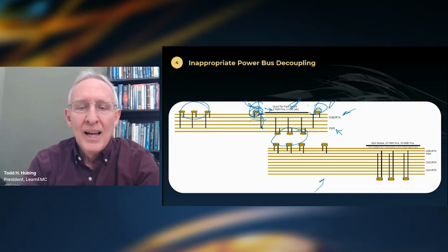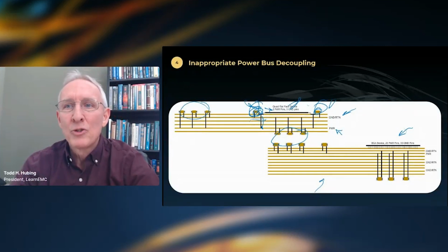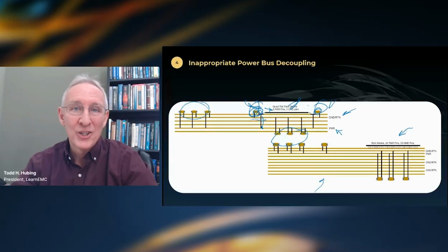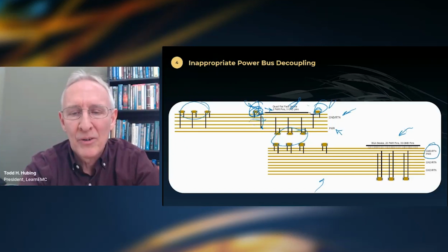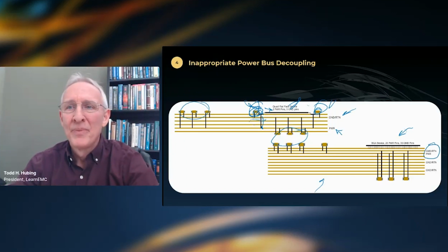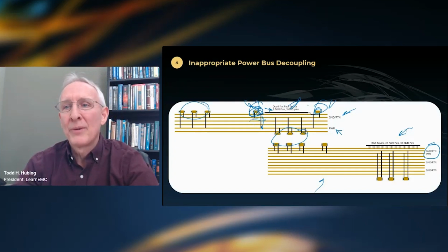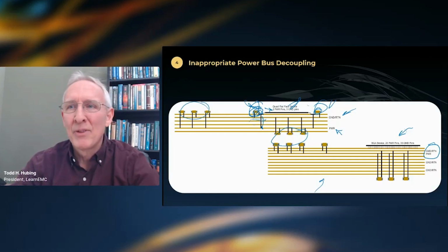Now, of course, here's a BGA device, maybe this has 300 pins and 20 of them are power pins, 30 of them are ground pins. Clearly, that's a device that needs a lot of charge fast. We can't put ground on layer 2 and power 3 or 4 layers away. We have to have power and ground right on adjacent planes, hopefully near the side with that active device. If I had similar active devices on the other side, I would also have a power-ground plane pair on the other side, but mostly we'll put all those really critical components on the same side of the board.